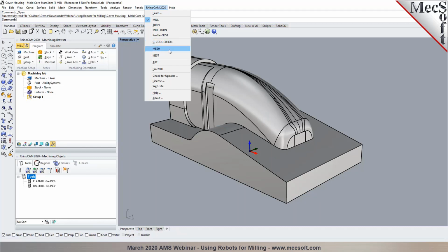The Mesh module offers you mesh editing, mesh healing, mesh repairing, mesh fixing, which can be used for CNC milling applications or could also be used for 3D printing applications, where you can also generate supports and export the mesh either as STL or G-code. We also offer parts nesting, where you can nest parts into a sheet, and also art, where you can convert art to part, which could be 3D reliefs, or you could do raster to vector conversions.